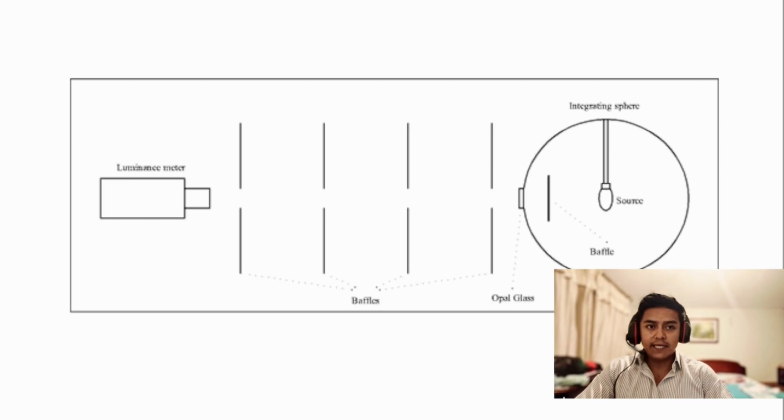A stabilized AC voltage source was used to reduce variations in the radiation source. The voltage regulation is 0.2%. The light source was an incandescent lamp, and therefore before taking measurements it was left on for 10 minutes to reach stabilization. With these precautions, it was ensured that the variation in luminous flux emitted by the incandescent lamp would not have a significant impact on the results.